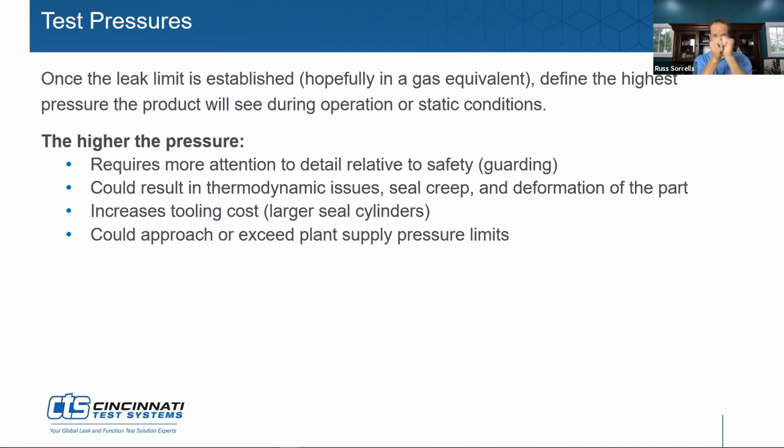We can't see those molecules, but they are absolutely interacting with themselves and heating up. Yep. And parts are going to expand, and we've even seen die castings expand under pressure. So the more pressure inside means it's going to be a little more unstable, and you need to stabilize for that. Yeah, in the past we put a dial indicator on a die cast part without pressurization. Then when you pressurize it, you can see that dial indicator increase, and that is going to change the volume. And so anything that affects the pressure inside of a part is going to affect the repeatability and results of the leak test. Yep, absolutely.